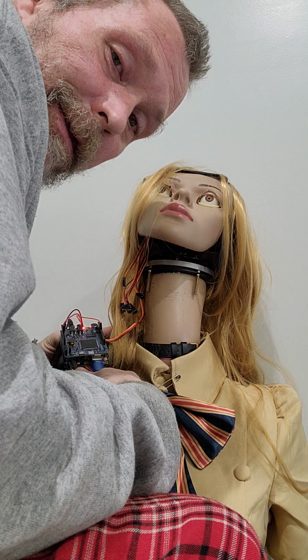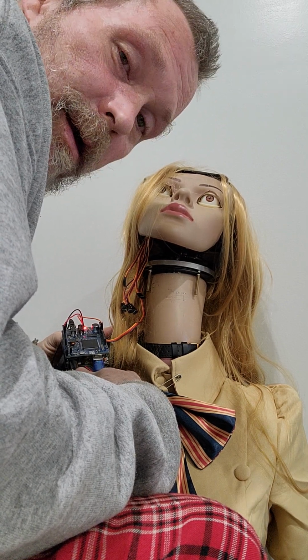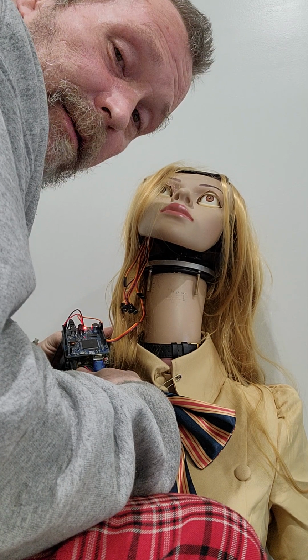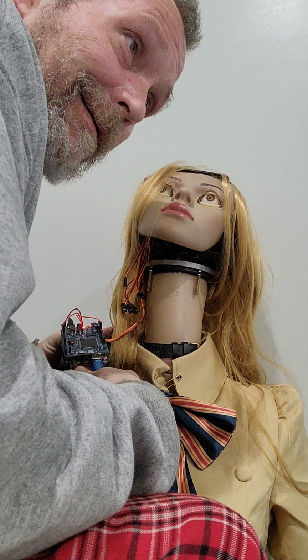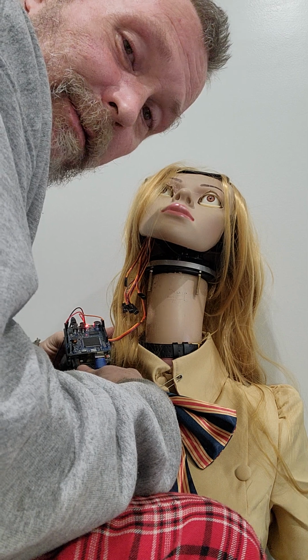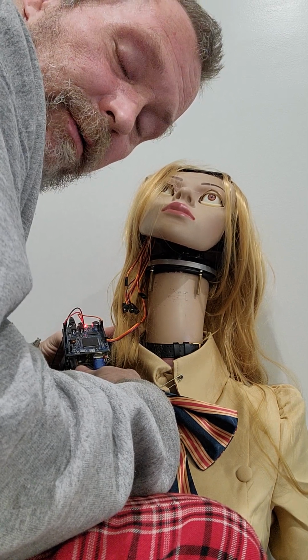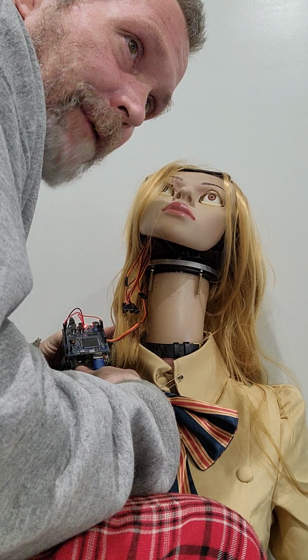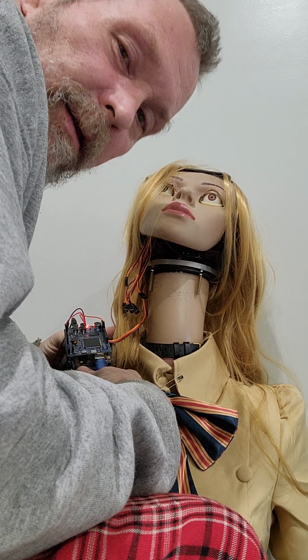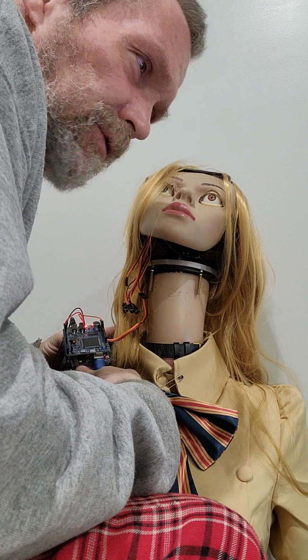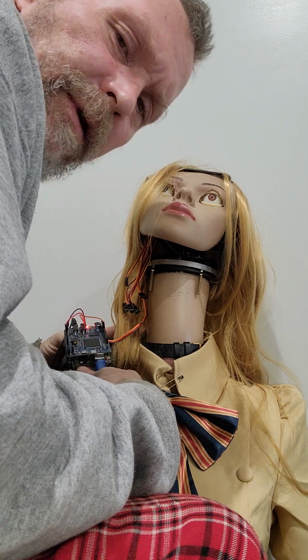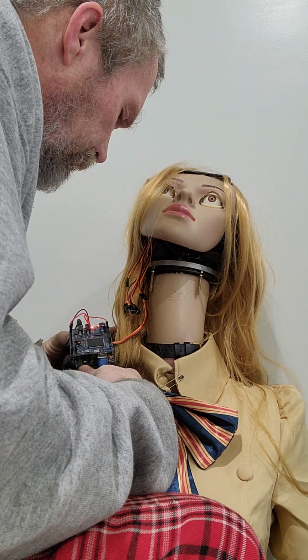We can go back and look at the code in a minute, but I think that's where it's going on at, and it's why I'm saying that we need to be able to figure out the millis and the array of functions to be able to put more servo to it. Right now, the delay function is blocking any other functions from being able to run, so we can go into more detail on that.